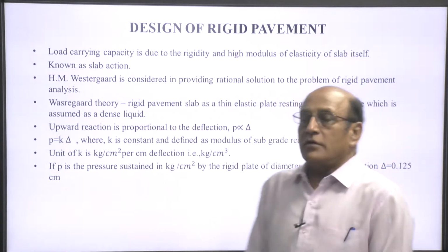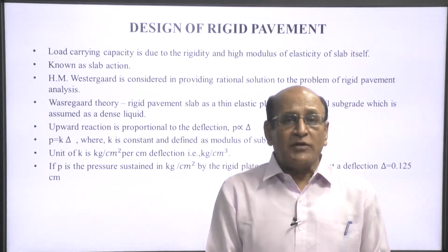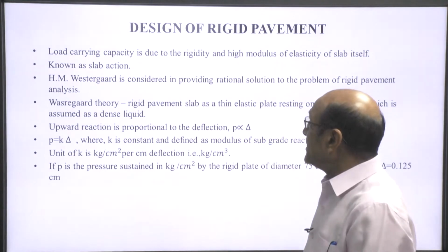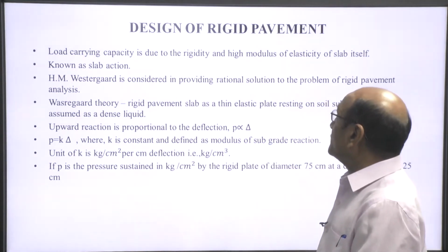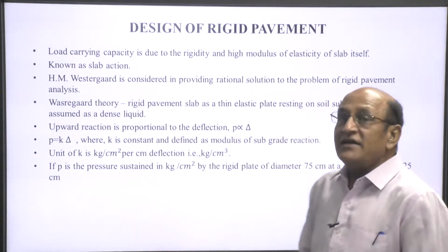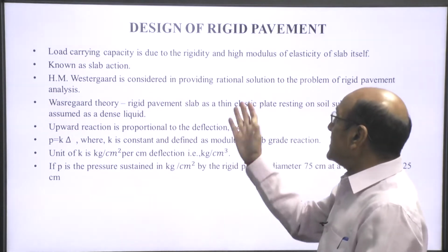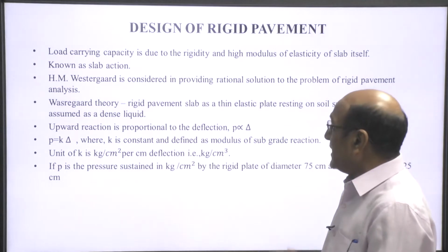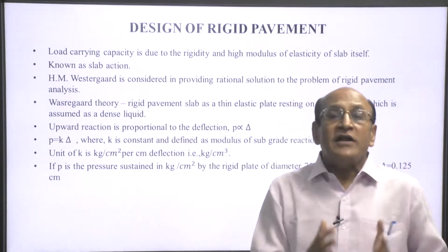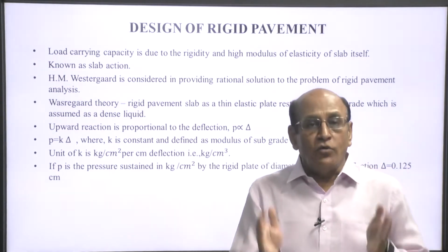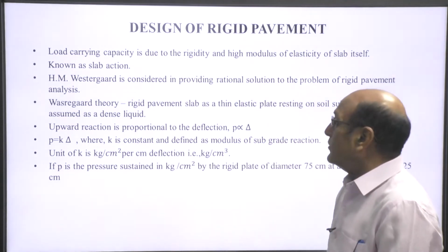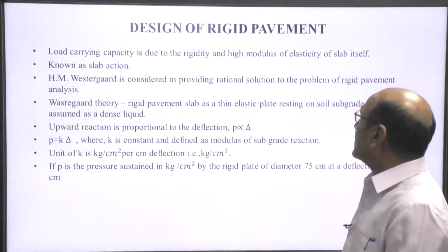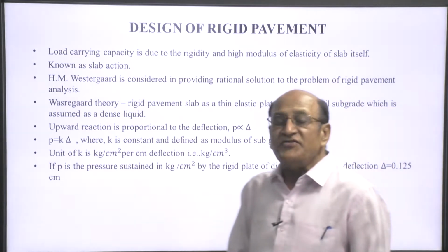As we know, in flexible pavement the load is transferred in a layer system, grain to grain. Here in the rigid pavement, the load is transferred by slab action, and the load carrying capacity is due to the rigidity and high modulus of elasticity of the slab itself. This is called slab action, by which load is transferred to the ground. H.M. Westergaard is considered to have provided a rational solution for the problem of rigid pavement.